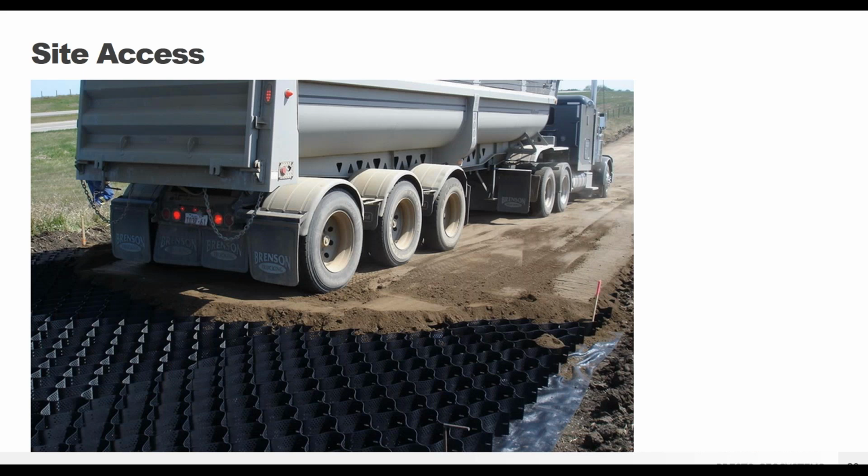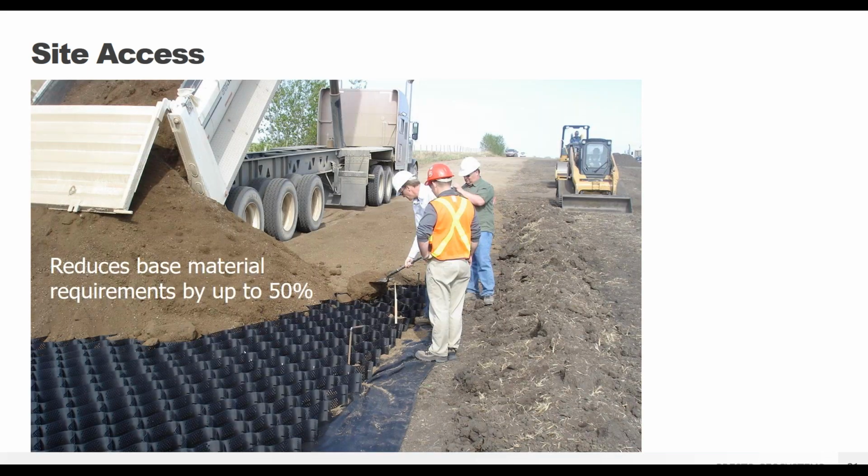Site access roads, both temporary and permanent, are probably one of the most common applications for the GeoWeb system. This project was created to access oil resources over undeveloped, soft, spongy soils. You can see how this heavy loaded vehicle can drive on the GeoWeb system immediately after infilling, to finish infilling as it goes forward. Like I said, you're using it as its own access road. So again, a good time saver in terms of construction.